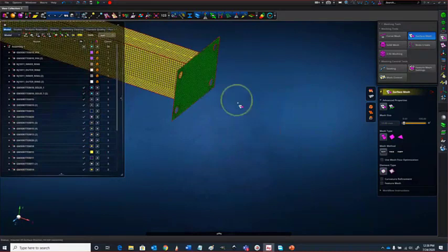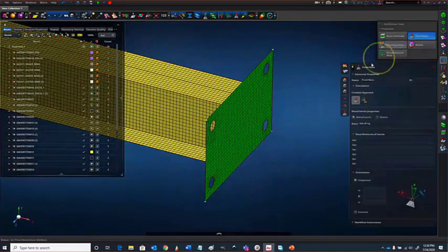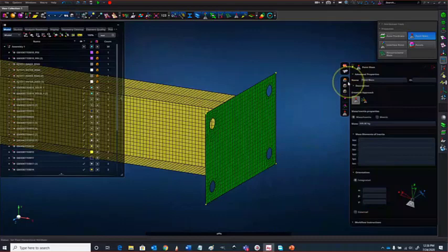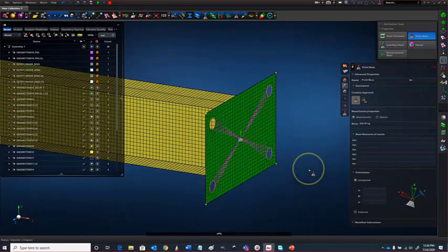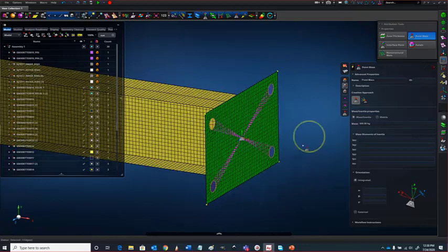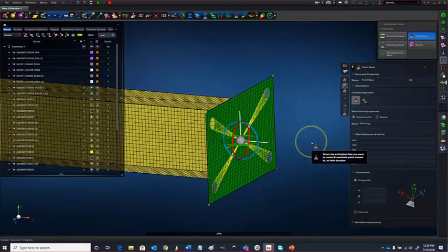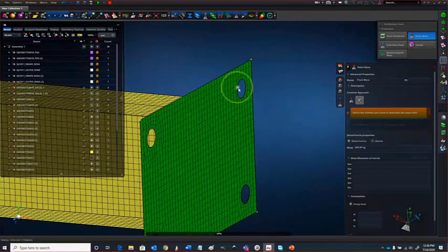And now to quickly demonstrate how to place a point mass at an arbitrary location. First of all, I've switched off the auto execute option so that I can select multiple locations like this. And the way to offset it, as you can see, by default it puts it in the center of the selected bodies, and we simply switch to this mode. I should have started with that, sorry. So let's just do that again.